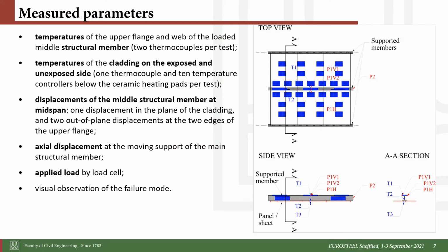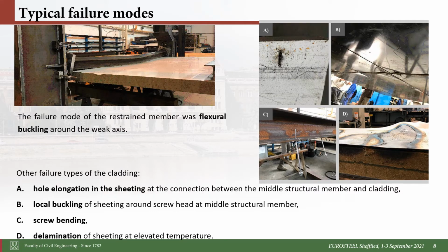We measured, of course, the temperatures of the member. We measured the temperatures on the cladding on both sides, the exposed and unexposed side. Of course, we measured the displacement of the members, the axial one, and then the in-plane and out-of-plane deformation at the highest point of the member. Here the axial displacement, and of course we measured the applied load.